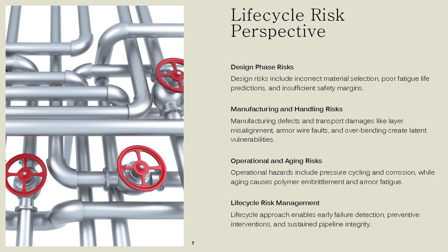Recognizing these life cycle phases allows engineers to implement targeted controls, such as prototype testing, real-time installation monitoring, and integrity management programs. By adopting a life cycle perspective, organizations can anticipate failure precursors, schedule preventive interventions, and maintain fitness for service throughout the pipeline's operational life.